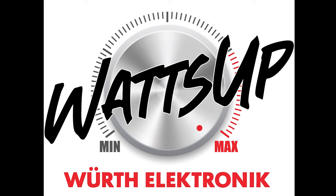Unshielded power inductors, such as the WE-PD2, can be used for uncritical applications or for low power circuits. Many packaging series can even be changed from shielded to unshielded versions while maintaining solder pad compatibility.